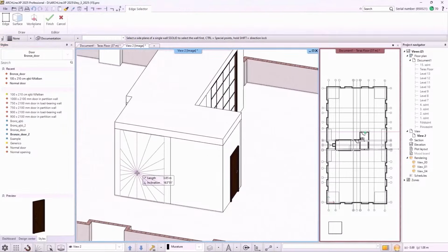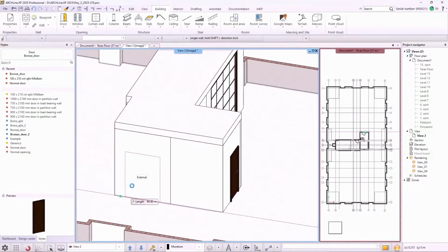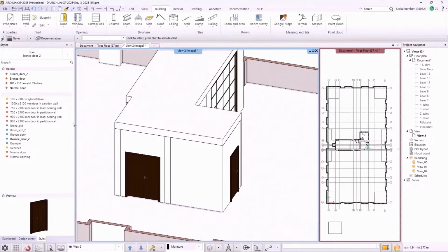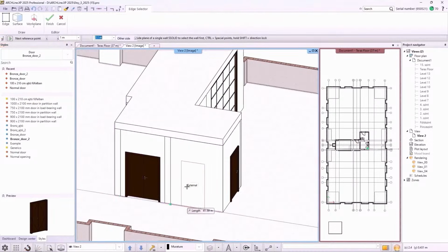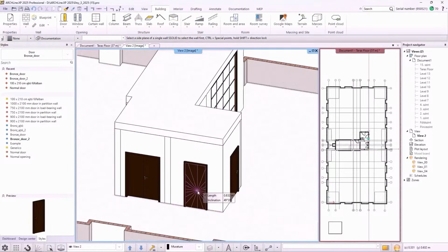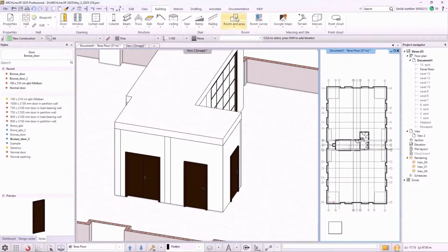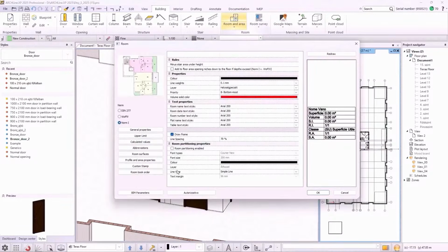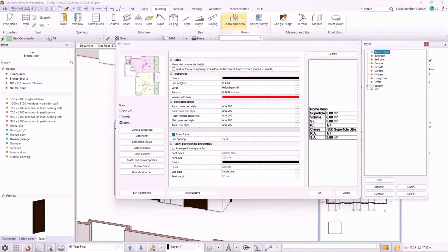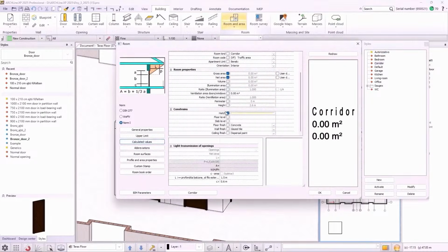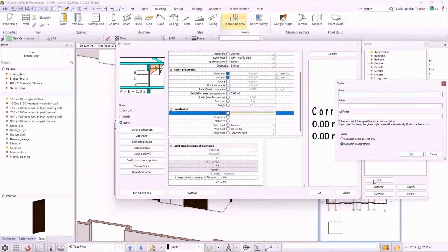This panel enhances your productivity by making it easy to use the elements and styles you want with just one click. You can also search for the style's name if you don't find it at the first sight in the list. When you create a new style in the Properties dialog of a command, it will be automatically listed in the Styles panel. Make the changes you want in the Properties dialog of the element, save it as a new style, or overwrite an existing one and close the dialog.